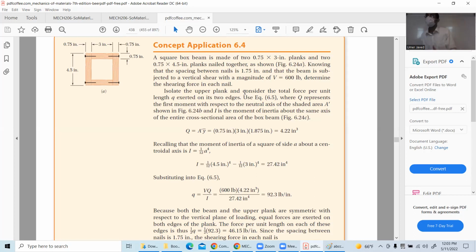The load is from the top, but the pin has the ability to shear from here. That doesn't mean that the load is from a different direction. If the load is from the top, how would this beam bend like this? Where would be the neutral axis? Like this. In the exam, I created something different. I put the load in two different directions, and that's why your neutral axis changed from here to there.